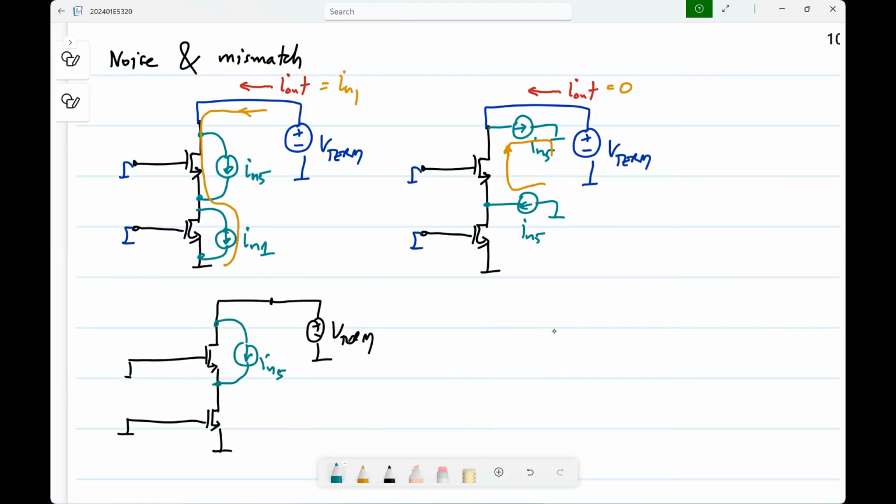Will it not have any change? Will nothing change? What is it that actually changes here? Why? No, no. The output resistance cannot change because of adding a source, right? The output resistance is computed without any sources. Is it likely that I add a current source to the circuit and nothing changes in the circuit? What is it that is changing actually?